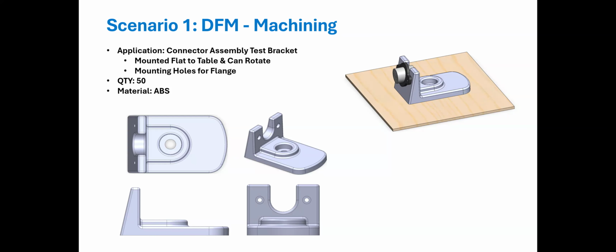All right, so there's one more thing. Let's see if you guys can figure it out. You have drafts on there, or angles. Are those functional, or can they be straight sides? Because this is another setup. The draft is functional. The brim, or the flange, of the connector is at an angle, so it just matches the angle of the connector so it can properly sit.